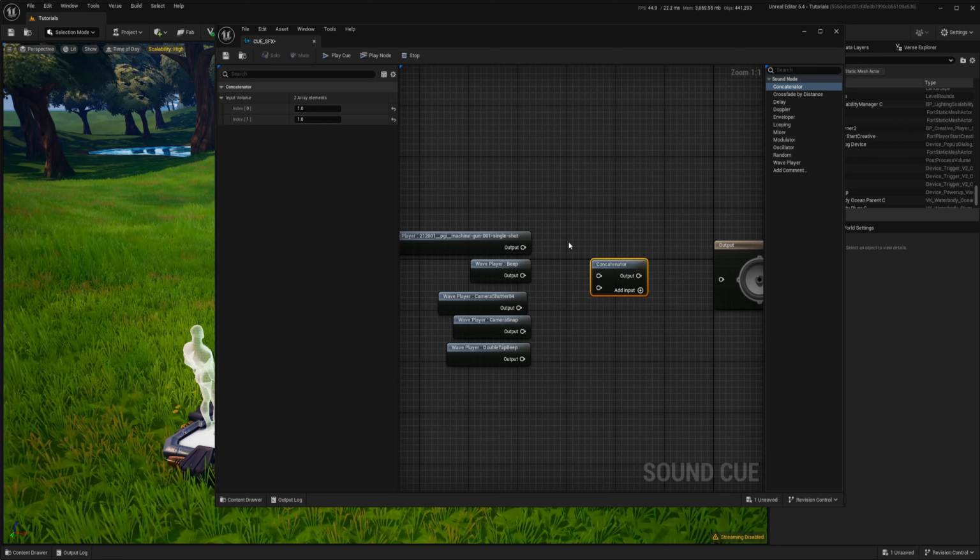You may notice that we don't have attenuation, but we have crossfade distance, and this can be used for attenuation, because we can add different audio, and in here we have parameters like in attenuation. When we want to fade in and fade out, the start and end basically dictate the falloff. It's really for a smooth transition instead of a sharp one. If you want the audio source to start playing really close to the player, don't change the start, leave it at 0. Then the fade out distance is where it starts to go lower and lower.